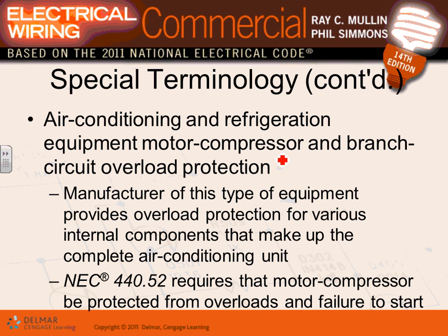Overload, guys, is typically provided by the manufacturer for this equipment. The manufacturer equipment provides overload protection, so we typically don't get involved in providing overload. All this is part of the manufacturer. But the manufacturer has to provide overload protection. So typically what we end up providing for most of the HVAC equipment is a fuse, a disconnect, and a feeder. A disconnect and a feeder.